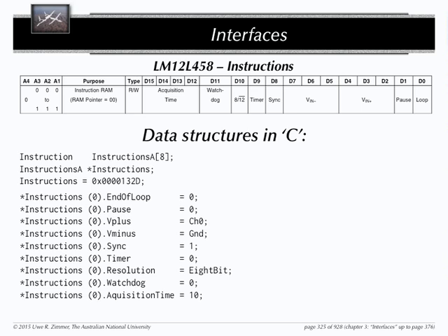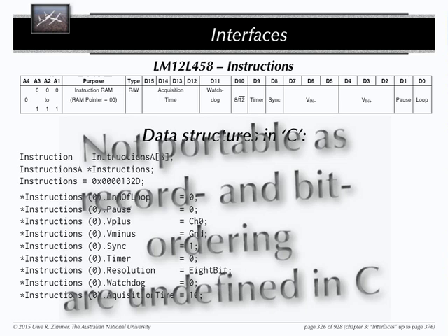Yeah, it looks okay, but it's plain rubbish. Don't do that. None of this is in any way portable. You have no guarantee unless you have a specific C compiler which is optimized for one specific microcontroller and does the alignment according to what you expect it to do. This is the definition of non-portable. C does not define record alignment, struct alignment, bit ordering in any way. And there are also no attributes, no pragmas to control that. So you can't do that.